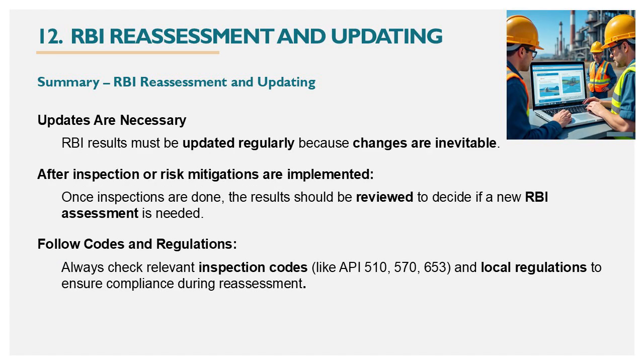Agenda number 12 is RBI reassessment and updating. RBI is not a one-time activity. We'll talk about the importance of periodic reassessment and updating the RBI program as new data becomes available. Summary of RBI reassessment and updating. Number 1 is updates are necessary. RBI results must be updated regularly because changes are inevitable.